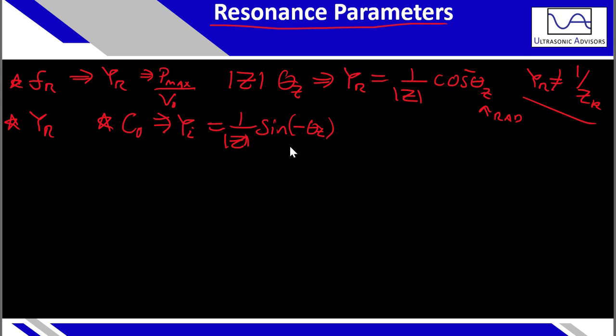Other things you could do if you wanted to look at the real impedance, so the absolute impedance minimum, you can also look at that and report the absolute impedance minimum too. So these will occur at a different frequency, not at the true resonance, but those are also significant parameters to record if you're trying to get a holistic understanding.